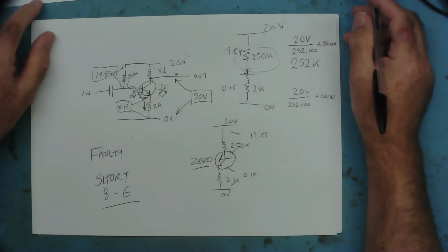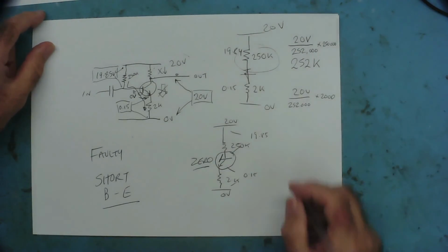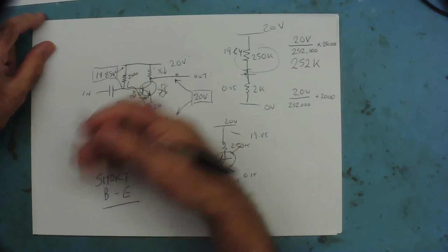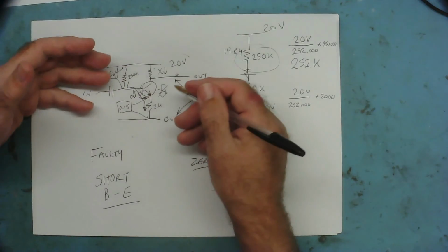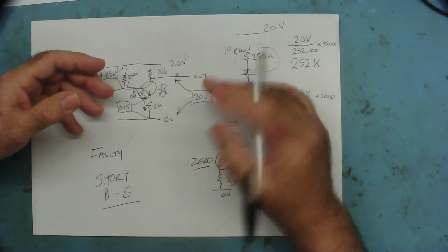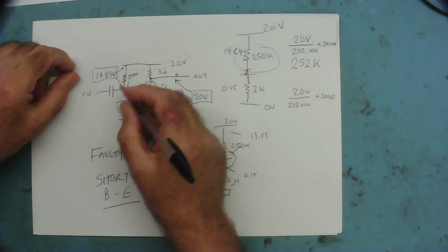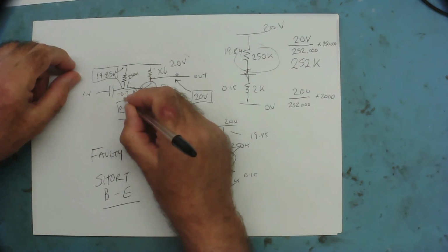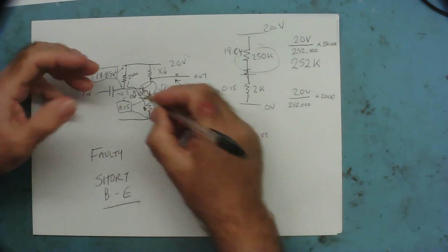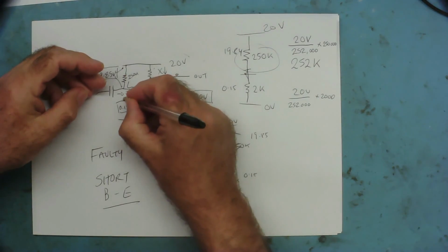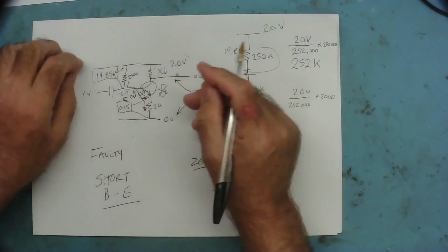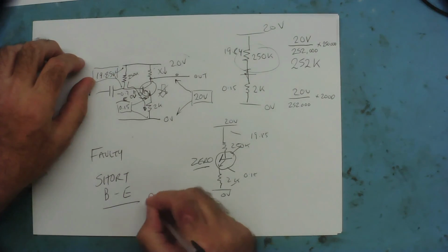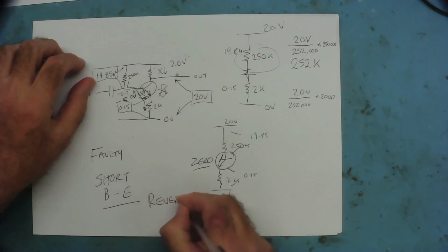One other thing I will mention before I go, and I will go after this. If we were doing all this with PNP transistors, it's the same. All these voltages are the same. It's just negative. It's back to front, yeah? So like your base emitter is minus 0.7 on the PNP compared to the emitter, yeah? Because people's brains, mine, and probably a lot of others, don't work well in negative voltages. If you're testing PNP transistors, reverse your meter leads, yeah?